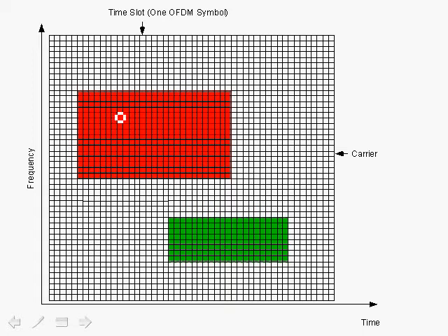Now here we're simplifying things a lot. In 802.16a, where we talk about OFDMA, we need to talk about FEC blocks, which are forward error correction blocks, which have to be on a certain boundary, and we'll talk about how to arrange the data in order to meet the requirements for forward error correction coding. But for now, just imagine that within this two-dimensional grid, in terms of time slots and carriers, we can have a data region which represents a burst of data. We can also define a region here shown in green, which represents a burst of data.